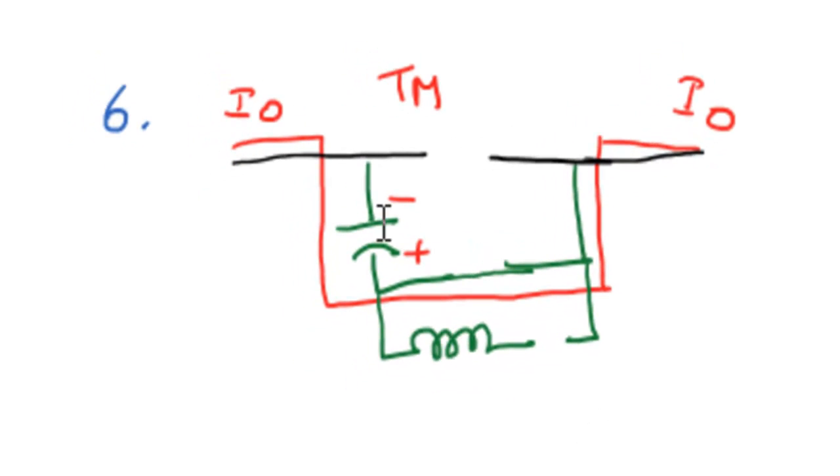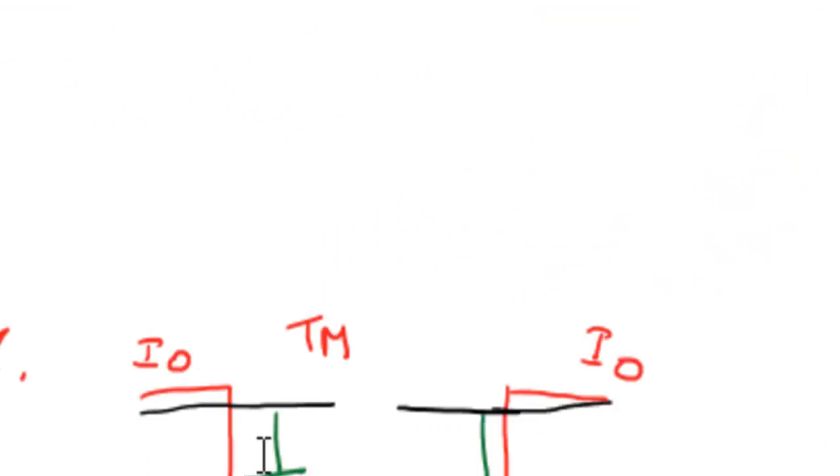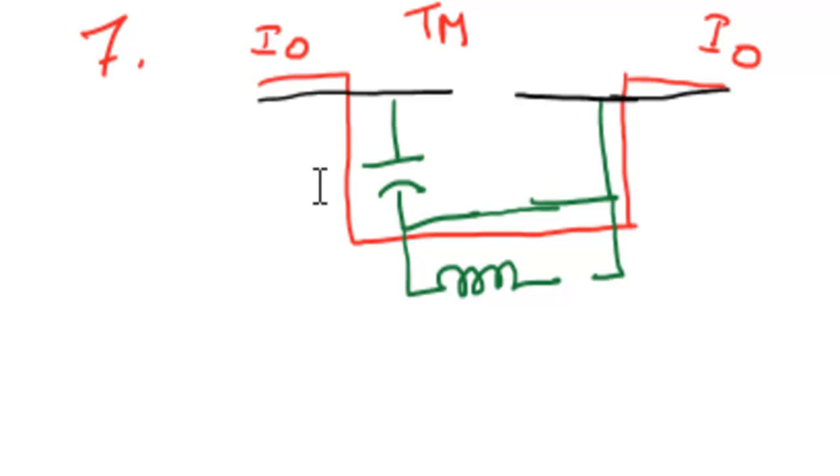As I told you, the capacitor is already charged, so it will behave like a voltage source, and the source is already there, so both are in aiding nature. That's why during this situation, the source and capacitor both supply energy to the load. That is nothing but the capacitor discharging with constant load current. Once it is completely discharged, the voltage across the capacitor becomes 0, like this. After this situation, the capacitor will start charging by the source itself.